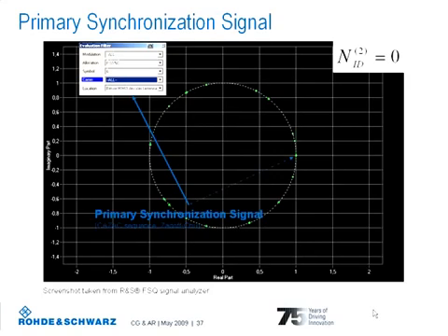The already mentioned match filtering works generally in that way that the received signal is correlated with the possible sequences for the primary synchronization signal. This procedure is not executed on the received analog RF signal. In fact, this happens in the digital domain. With successful match filtering, the device has identified the used physical layer identity for this cell as well as 5 millisecond timing. Afterwards, it can execute the next step, looking for the secondary synchronization signal and the physical layer cell identity group to compute the cell's identity.